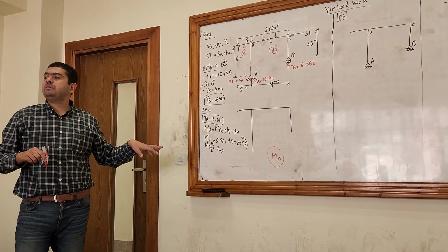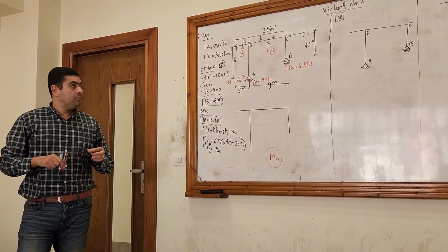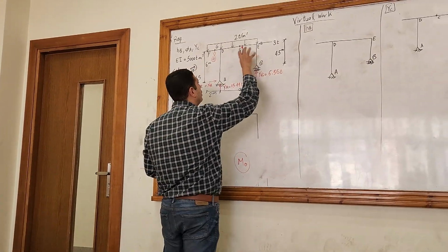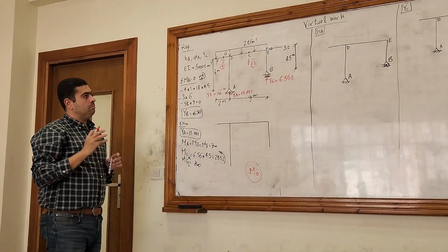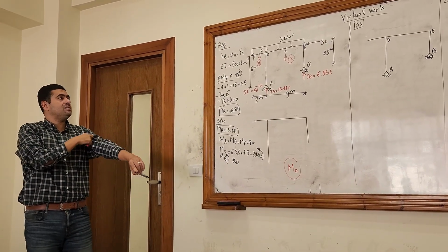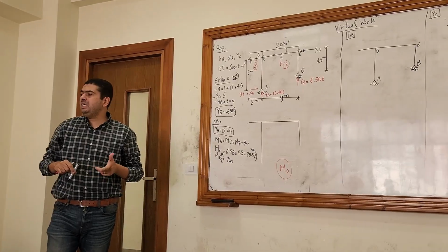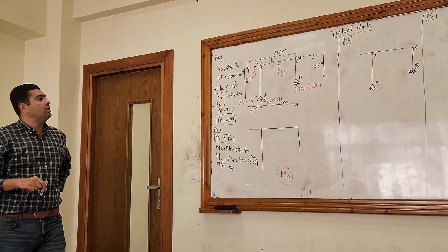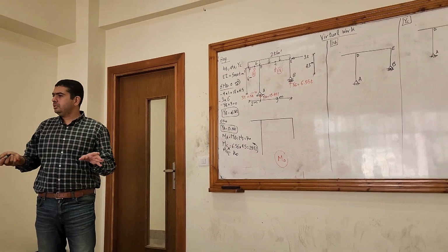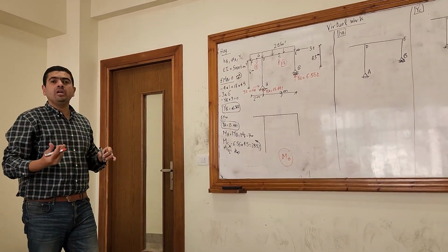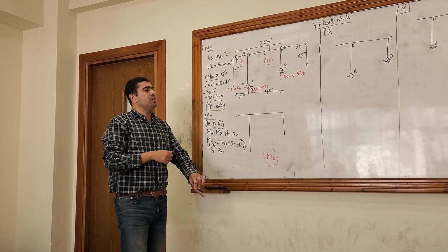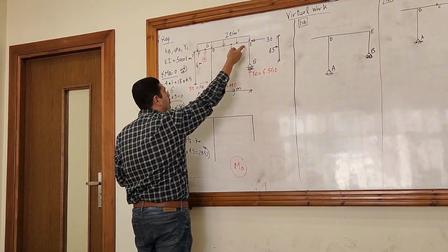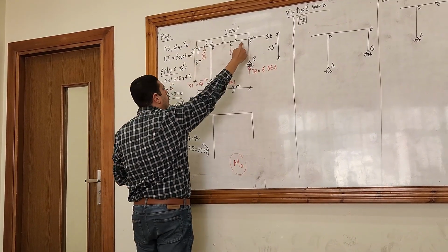Now I want to calculate the moment at the joint. How do we calculate the moment at the joint? First of all, you have to put the moment of the joint here in the main example. Let's start with the easier joint. Which is the easier joint, E or D? E is easier because it only has 2 members, and D has 3 members. How to calculate the moment at E? It's like a regular point, right or left, okay? But here, it's a joint. So you have to decide where you will calculate the moment at D from: from EB or from EDFA, which is easier?